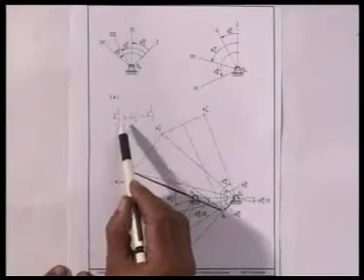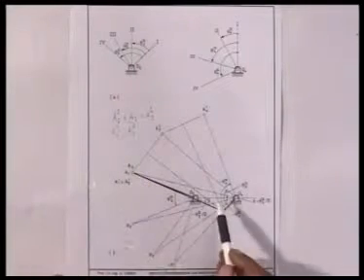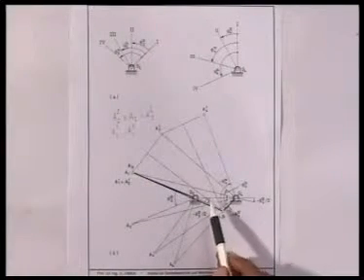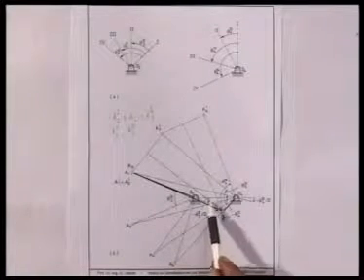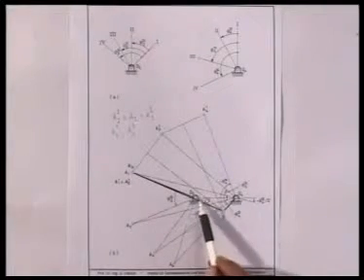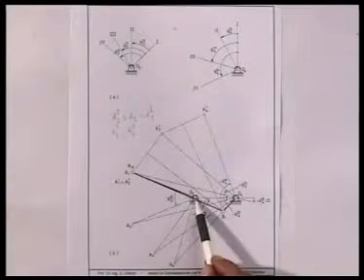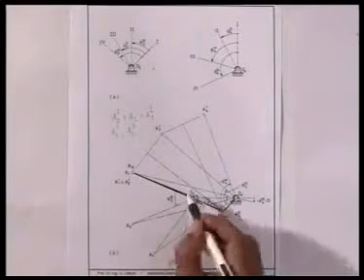To make A21 coincide with A1, I choose A1 as follows. I draw a line at an angle minus theta 2 1 2 by 2 with O2 O4 at O2, that is this line.